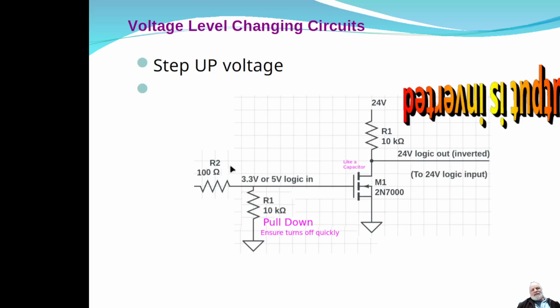So this resistor is going to have to drop the rest of that. And so if you're using a BJT, you got to pay more attention to your current and the values of resistors. So usually a 100 ohm in that case would be too small. But you don't put the pull down resistor with a BJT. You don't need it.